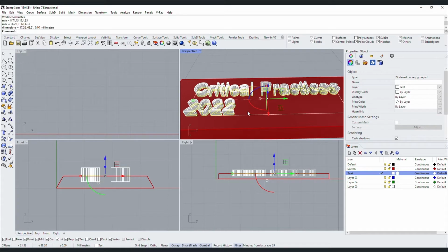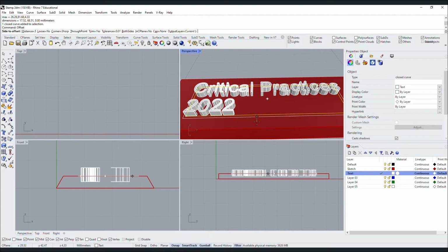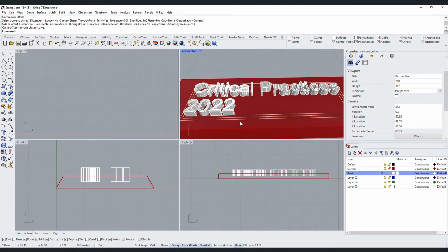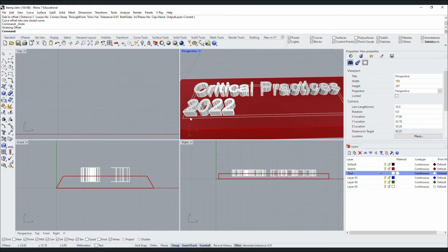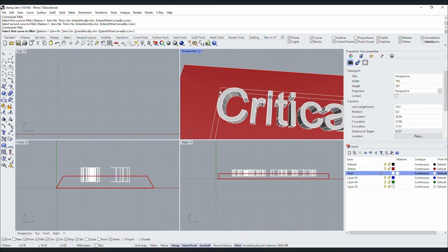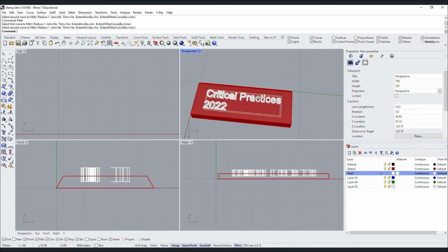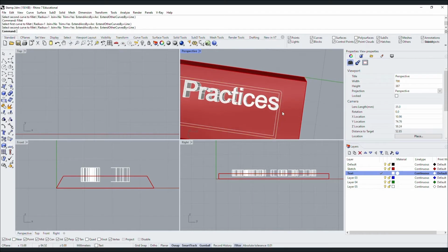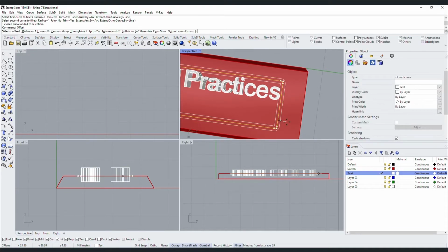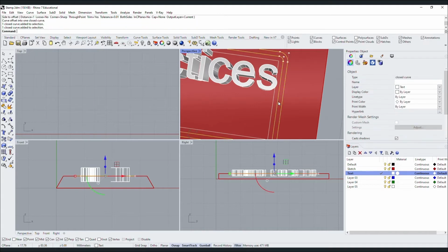I'm going to select the curves and create a bounding box because I need a frame outside, just a design thing. You can skip this step. I'm going to offset it, and first let's do fillet command so that I have a rounded edge. That you can do by fillet command and then select one edge and the second edge and select the radius. So that's how you can get a curve boundary like corner.